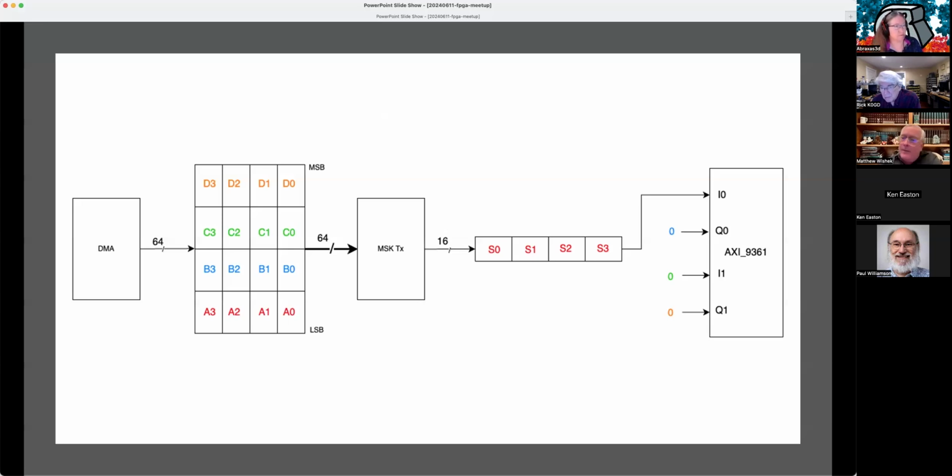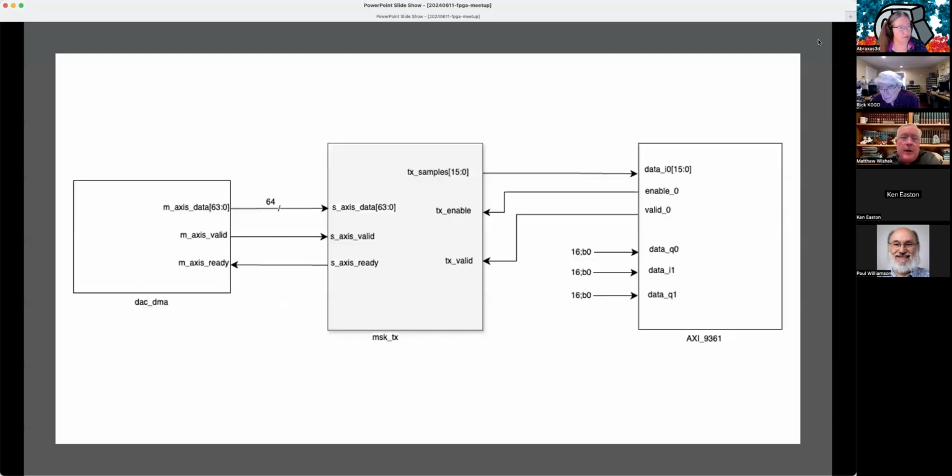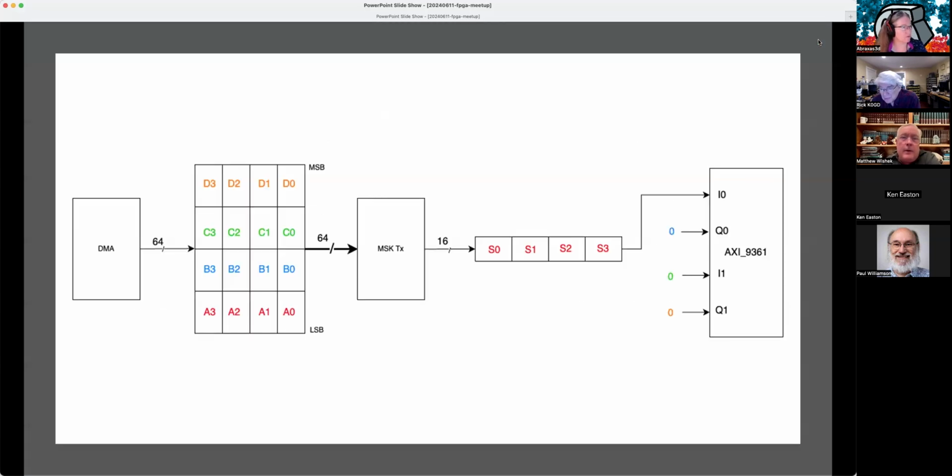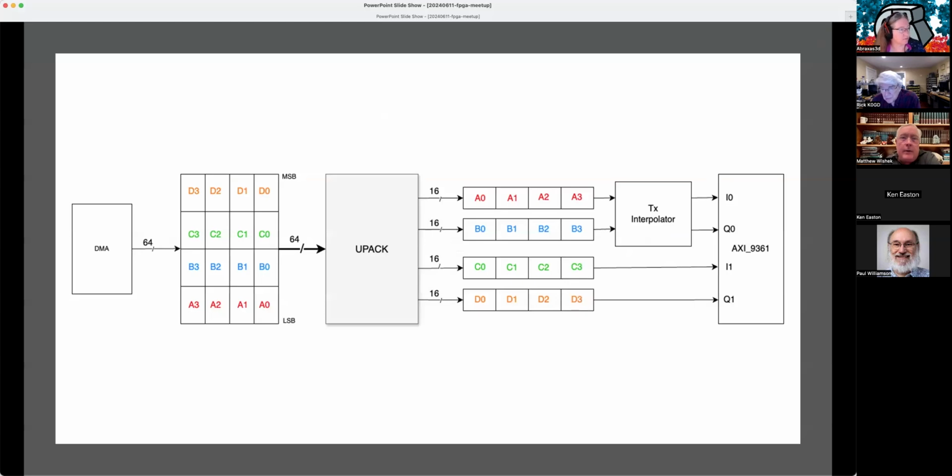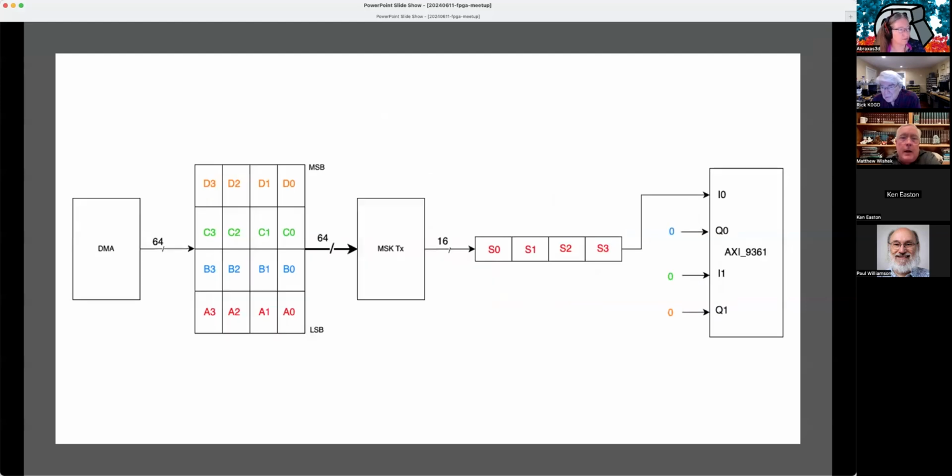Oh, well, I'm still looking at the sample rates. I'm trying to determine if we need an interpolator. There's really no reason that we need an interpolator. We're just highly oversampled, and there are no accumulators or anything in the modulator that should particularly require an interpolator. So I think we should be able to get rid of it, but I just need to run some more simulations.